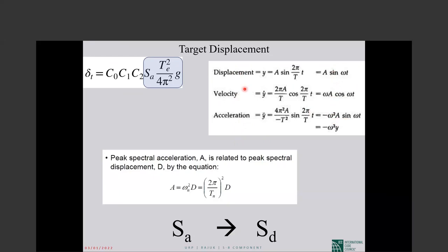So interesting. So if you have the response spectrum curve, you easily can calculate the maximum acceleration of this building.